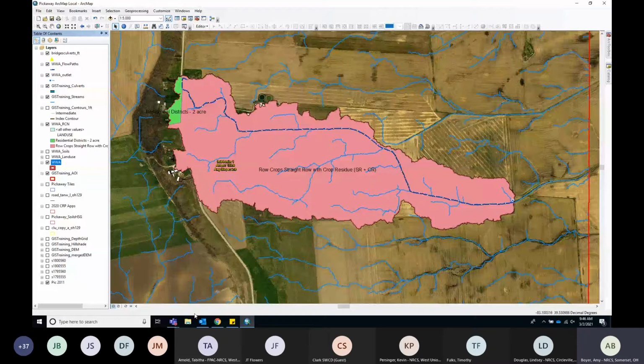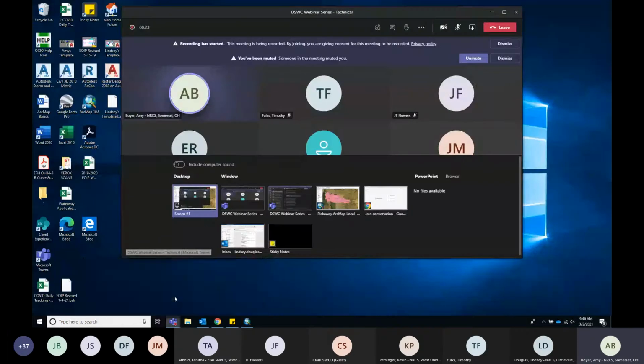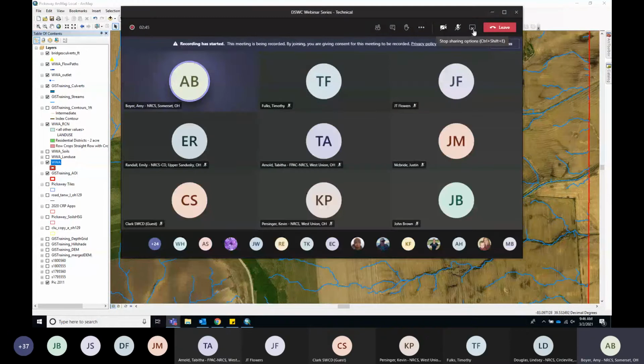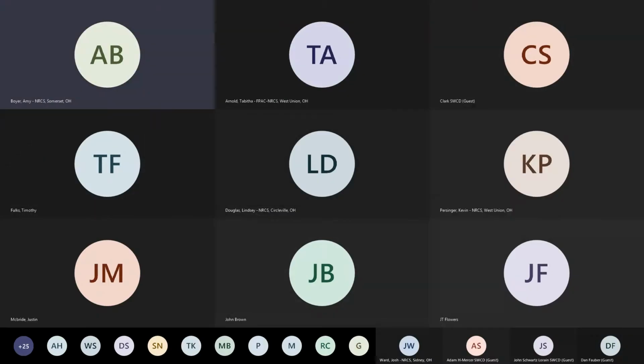And what I'm often going to do is put this into the web soil survey, because I find it's usually the fastest way to break down my different soils. So you can just start web soil survey, and we're just going to touch a little bit on what this program can do. I know next month we will end up going with Matt Lane with ODA, and he'll go very far in detail on this. But the only thing we're interested in today is the area of interest and importing our area of interest. So we're going to create an area of interest from a shape file.